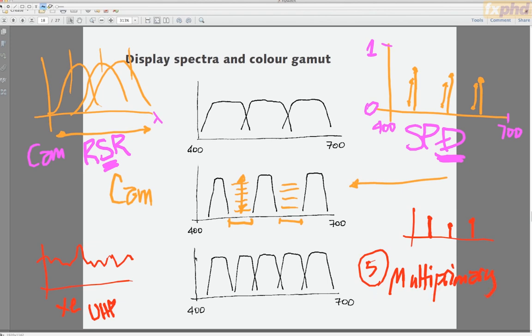And the effect on the chromaticity diagram is basically that you produce primaries at various points, and then you stitch them together in some kind of polygon to get the gamut coverage. But as lasers become more economical, multi-primary becomes less interesting.